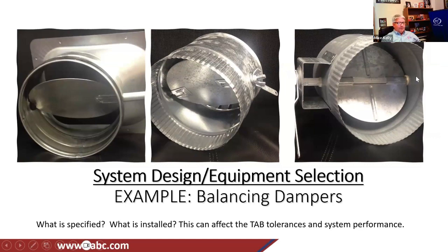This solid shaft over here to the right with the standoff is a great damper, but again, depending on the system and the velocity and how oversized it is, or how much you have to damper, these do move as well, along with the one here to the left. I like the flange part, but I have known this to be true: sometimes they have put this on the duct, cut the round on the left side here, or the left picture.